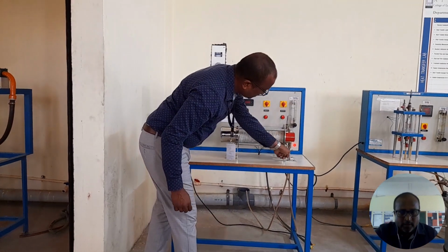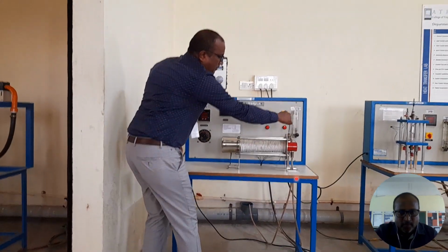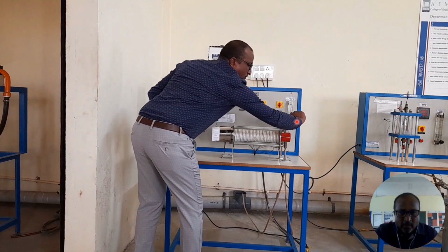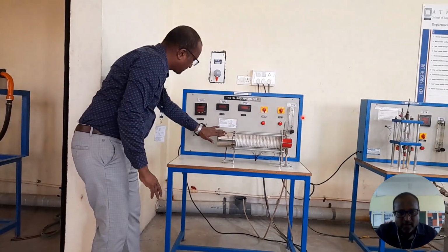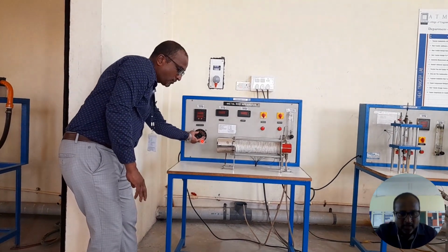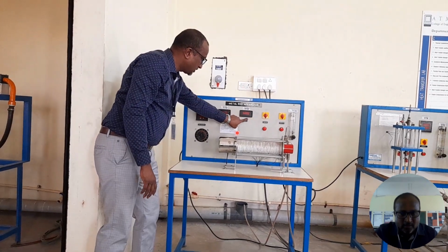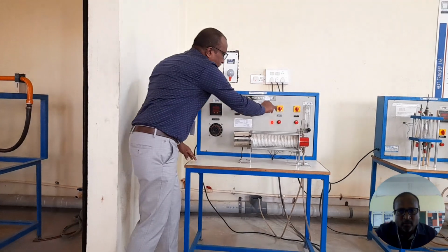And the cooling water is flowed through the pipes here, and the flow rate of that can be adjusted using that knob there. You can turn it to increase or decrease the flow rate of water. Similarly, the rate of heating can be controlled by this dimmer stat. By rotating this knob, you can vary the voltage and current, thereby rate of heating here. And this is the place where we are going to read the temperature.